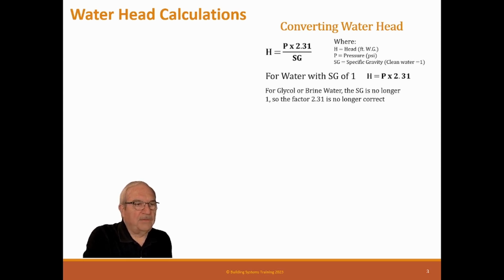Now those are kind of important because in HVAC engineering and equipment, most things are in feet of head, not PSI, except for pumps and whatever, but even pumps are head. So we got to work our way between those two. And so that's a formula to use all the time.